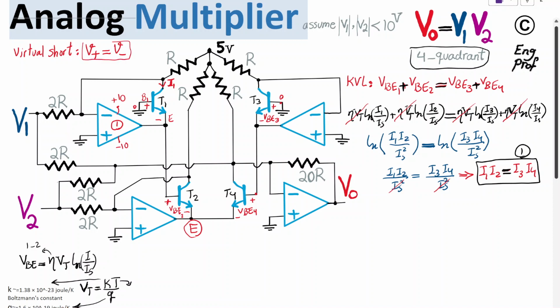So given this, the voltage at the positive terminal is 0, connected to ground, therefore a virtual ground appears at the negative terminal, making the voltage here 0 as well. So that is exactly 0 volts here. That makes my life easy because I can easily find this current, let's say current IA, and this current IB.